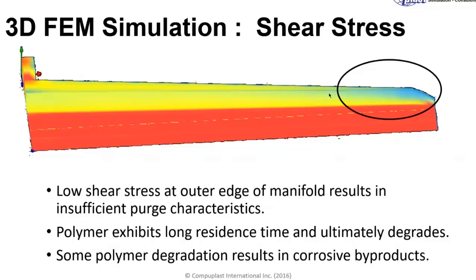And that's how we determine the absolute minimum shear stress that will maintain the surface clean and avoid stagnation and degradation. We put a little safety factor on that, and then we tell our equipment supplier that the next die you build for us, we want you to ensure that the shear stress on that surface is above this critical value, and that will greatly reduce the number of times you need to take that die down and send it out for refurbishing.